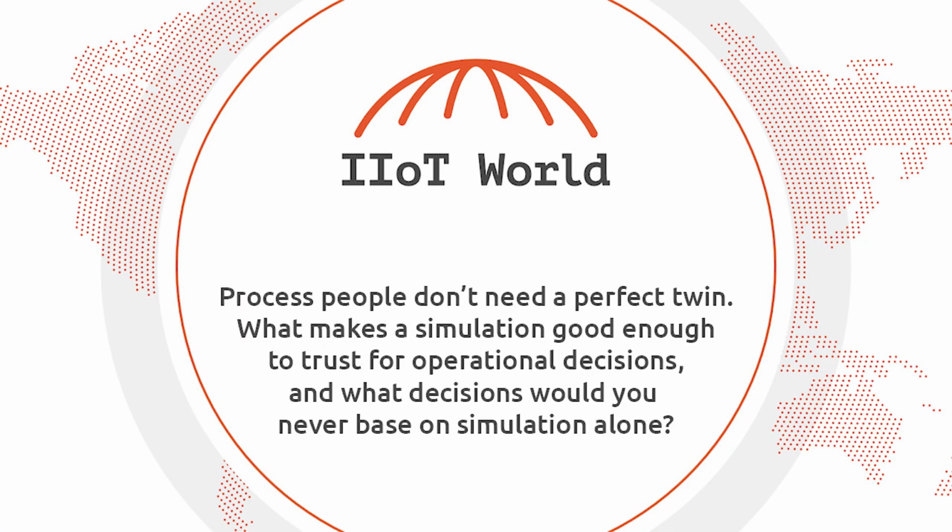Now, process people don't need a perfect twin. What makes a simulation good enough to trust for operational decisions, and what decision would you never base on a simulation alone? First of all, when we say a simulation's good enough, the measurement that I generally use is that I will compare the output of a simulation and the output of the real production data. So first of all, you have to have alignment in terms of how you measure it.